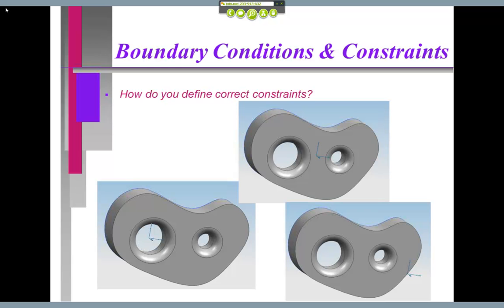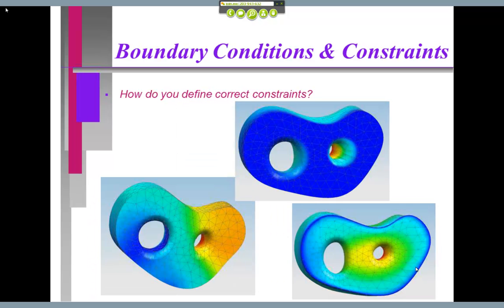And so the challenge that you have on this car project is to figure out which of these types of constraints you want to use. It'll be different whether you're looking at an A-arm, the chassis, or the structural supports for the solenoid, the engine of the car. You're going to have to come up with the correct way to grab hold of the components to get believable results.